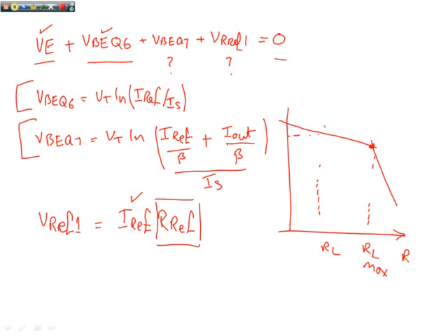That's RL maximum, so you're going to determine that. What I would like you to tell me is this gradient. You've seen the basic simulation before with the basic mirror. What happens with the beta helper with emitter degeneration? Does this gradient improve, get worse, stay the same? Those are the big questions that you've got to answer today.